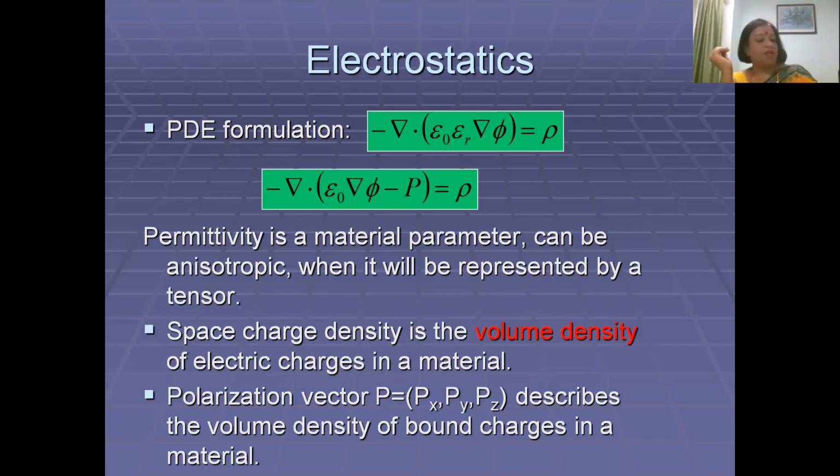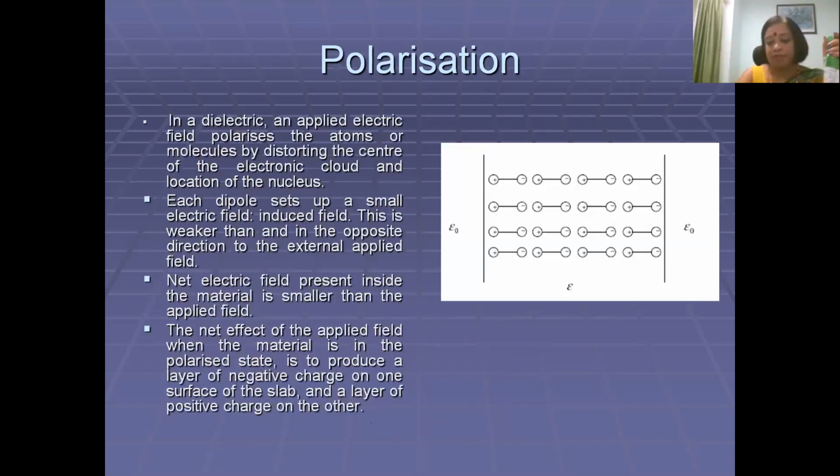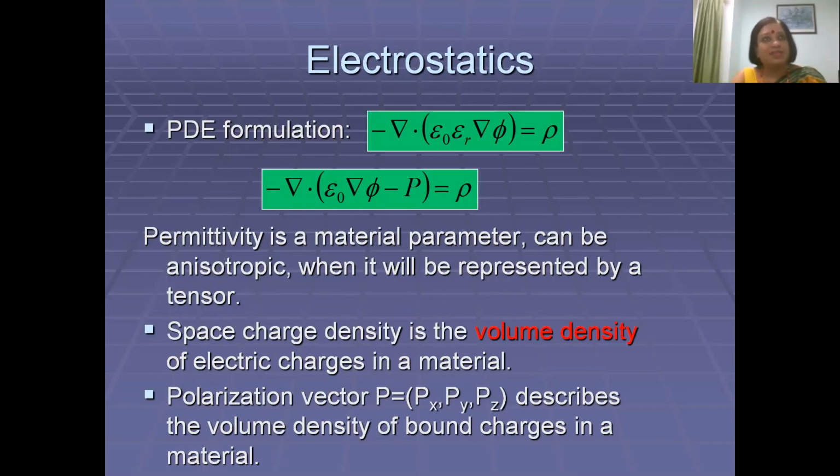There is also another reason why I am starting from this perspective. You have already been introduced to COMSOL yesterday, and you will see that COMSOL allows you to solve electrostatics and magnetostatics by name, but it also gives you the option to choose whichever partial differential equation you wish to solve. So you can take your own partial differential equation and solve it using COMSOL, if you know how to frame it, even when a user-friendly GUI is not given.